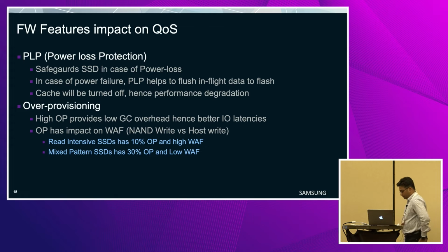PLP has an impact on the performance, particularly on the QoS side. First of all, what is PLP? Power loss protection in SSD. It safeguards the SSD in case of power loss. Normally SSD vendors provide some capacitor, so in case there is a power failure, the capacitor will sustain for some time. It will provide the power so that your metadata will be synced, and it will safeguard your SSD.